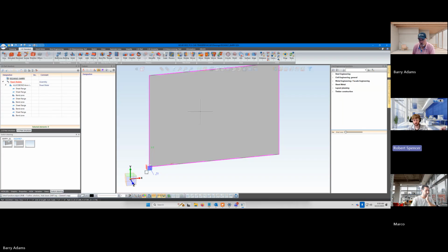Then you go back and make a change to the panel, whether it's minor or major, it doesn't matter. You need to save it again and then update the elevation model with that create new option that I just showed you a minute ago, that you possibly already forgot about.